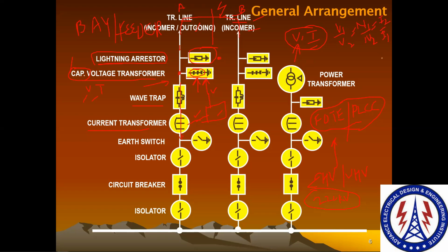In the same way, if you remember, the capacitor voltage divider rule. Suppose you want to measure the voltage across two capacitances, C1 and C2, with V the complete voltage. The voltage across C1 will be given by C2 upon C1 plus C2 times the voltage across the complete V. So you see the voltage across C1 is directly proportional to the capacitance value of the other capacitor.